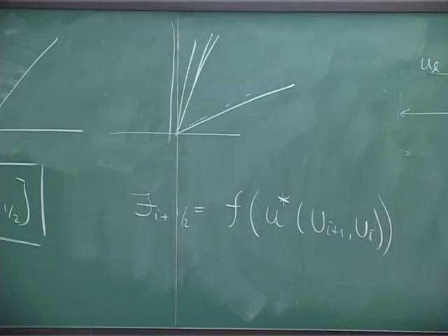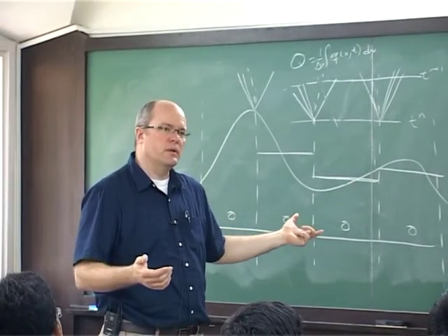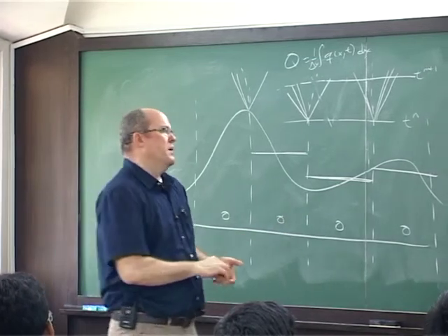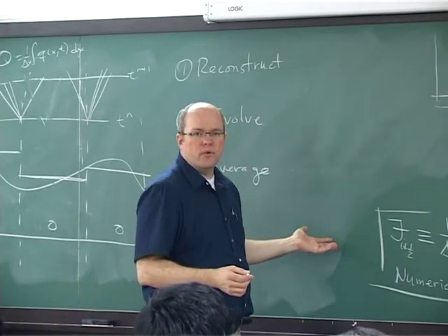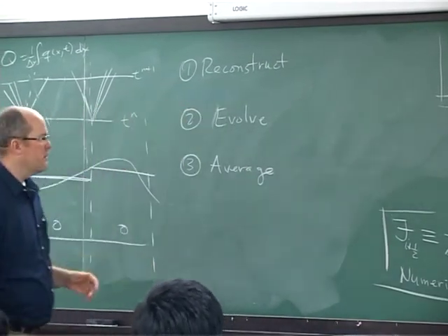This is really a big advance, and almost all of the fluid methods that we use today for compressible fluids with shocks are based one way or the other on Godunov's method. Godunov's method is still a very dissipative method. It's a first order method. It's like upwind. In fact, if you do Godunov's method for an advection equation, it just turns into the upwind method. But we have some things we can do to improve Godunov's method, and we'll talk about those.